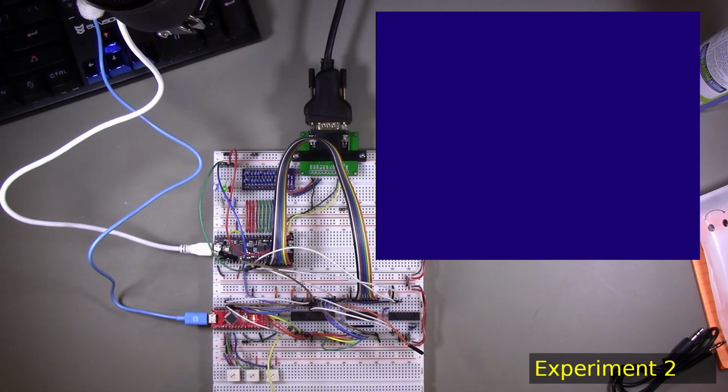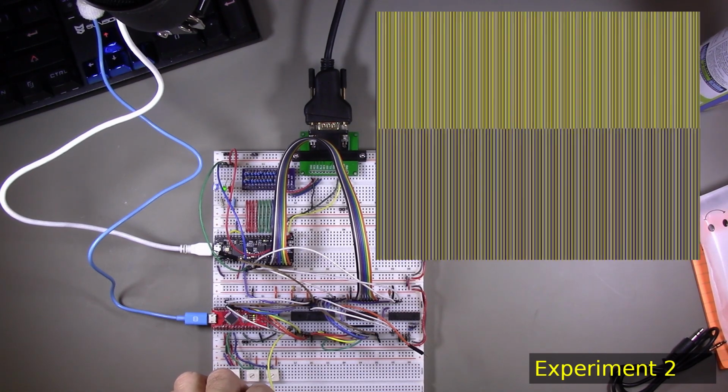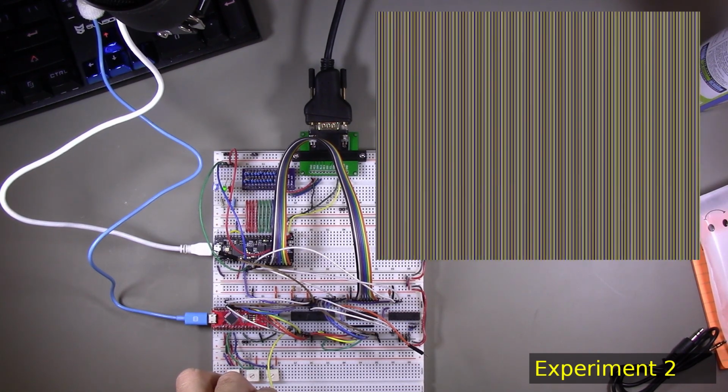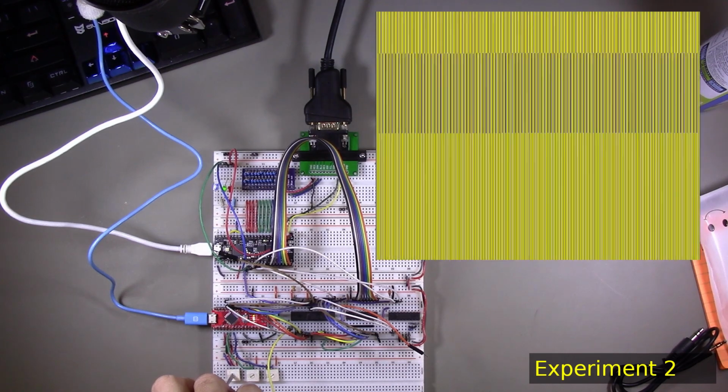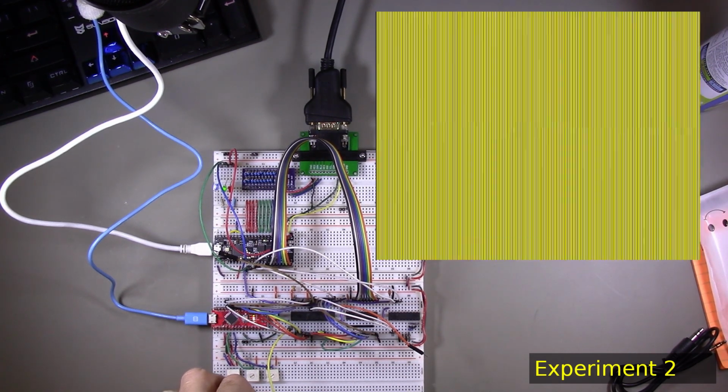What this experiment actually does is, as I adjust this potentiometer, the Arduino will send bytes of data to the display controller, which in turn will put them into pixreg, and then they will get output on the display. So again, flashing video warning as I adjust the potentiometer here. Basically, every byte of data is rendered as groups of 8 pixels on each line of the display, and so as I adjust the potentiometer, I get different values, and they are displayed.